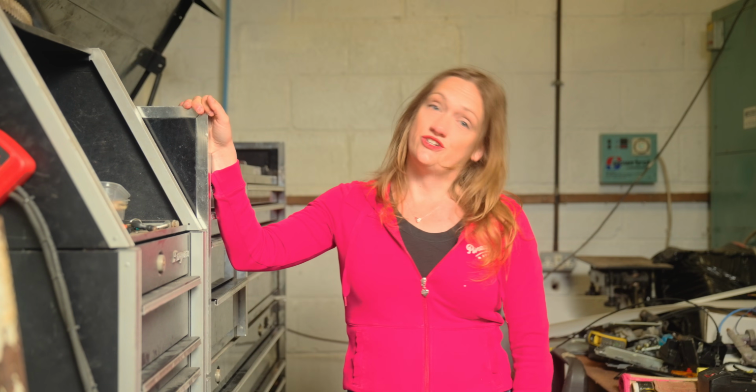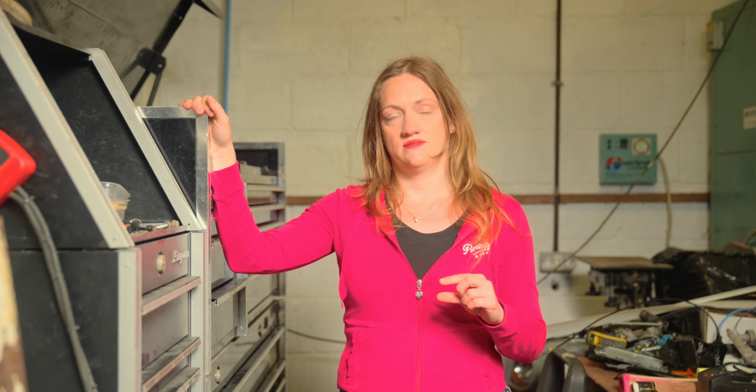One of the things I chose to do on this job was to lock the flaps in the middle position. Most people don't bother doing this, and it can cause issues with the car. If the flaps are fully open, the car gets maximum performance, but suffers with poor starting and low torque. If the flaps are fully closed, it suffers with hot start issues and doesn't have the top end performance. By setting them in the middle position, it's a balance between all of these factors.